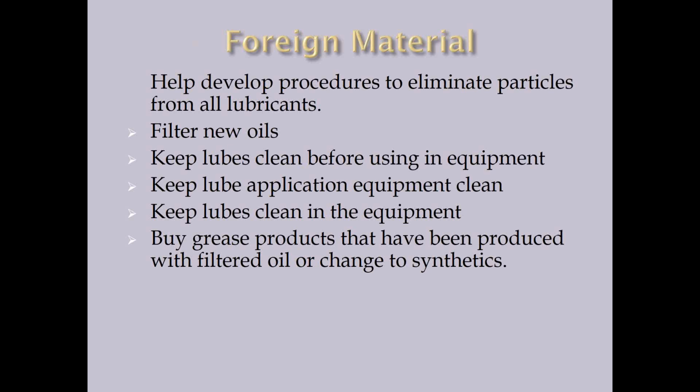So we installed a dishwasher in our shop, and every Friday the guys would wipe as much oil out of the container as they could. They would put them in the dishwasher, come back in Monday morning, and you had brand new oil-safe containers. Keep your lubes clean in your equipment.